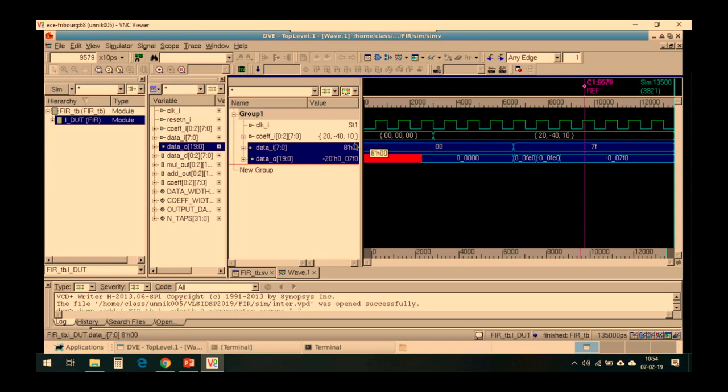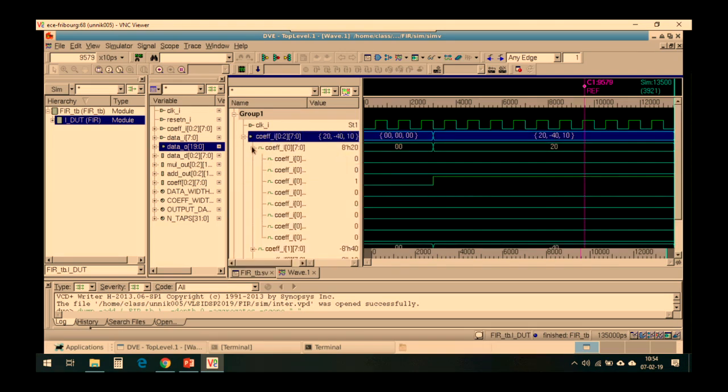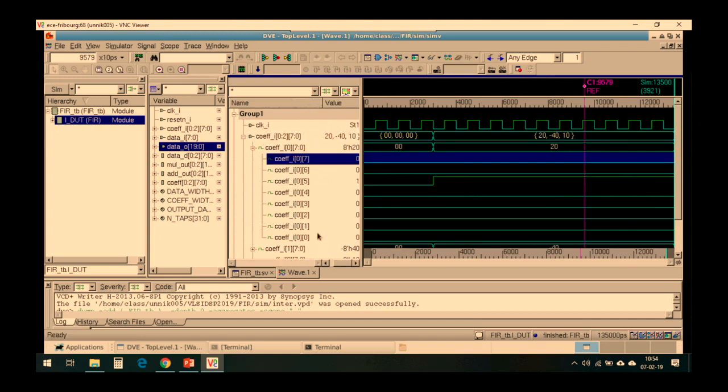But in this scenario, how we interpret this bus is that the high MSB bit will be the sign bit, assigned in this particular case the value of -1, and every subsequent bit is a lower power of 2. For example, the first bit is 2 to the power 0, then 2 to the power -1, 2 to the power -2, 2 to the power -3, and so on.